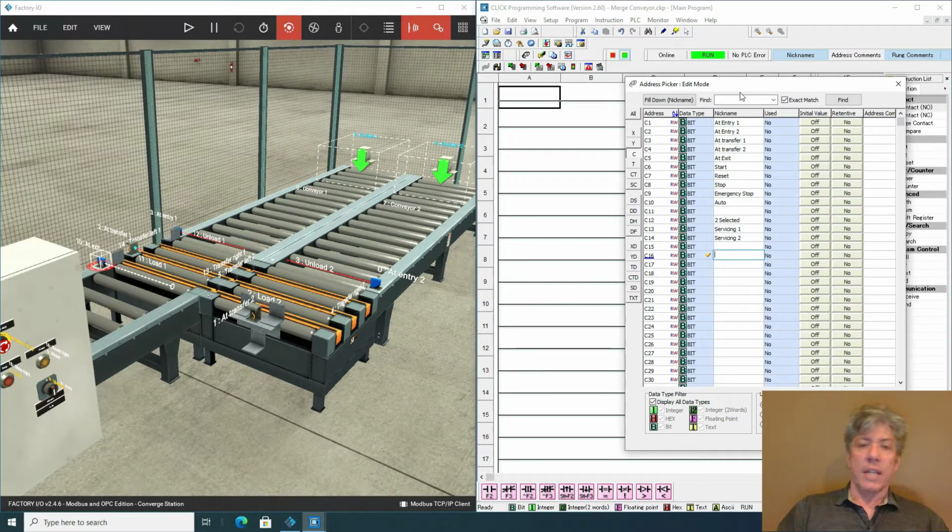And what I'd really like to do is just have maximum throughput, just have pallets running through here as quickly as possible. And so if there's something available from conveyor 2, I want to send it on. If there's something available from conveyor 1, I want to send it on. But what if, I mean, it's pretty easy. If there's nothing available in conveyor 1, I just send through whatever's coming through in conveyor 2, and vice versa. But what about the case where we have something available from both conveyor 1 and 2? What would I do then?